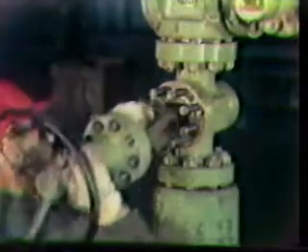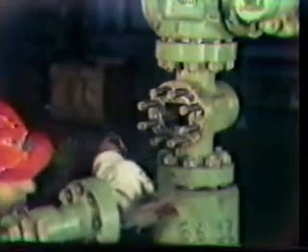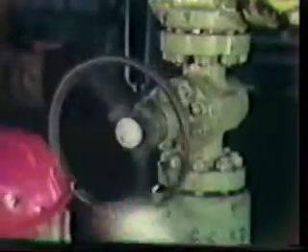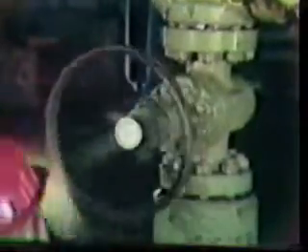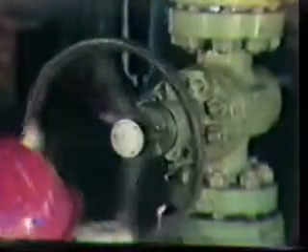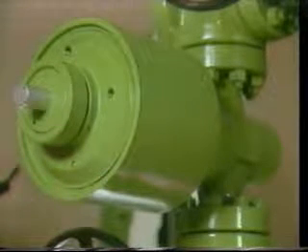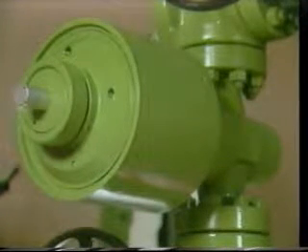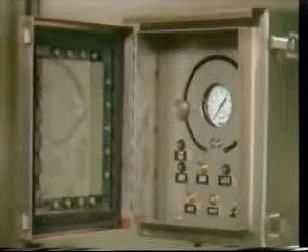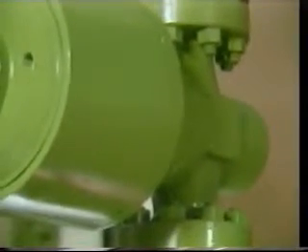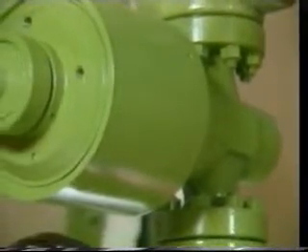Therefore, a gate valve should be chosen with some consideration given to repair or rebuilding procedures. Note that over-torquing a valve in the open or closed position may cause undue stress on the stem and can reduce the useful life of the valve. A safety valve or activated valve is often installed on gate valves to prevent continued flow through the valve when downstream pressure becomes abnormal. The activated valve, termed actuator by the API, is fitted on top of a gate valve